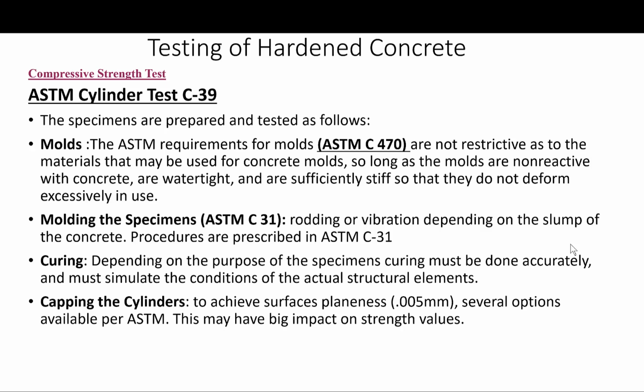If you refer back to the testing lecture early on in the first module, okay? For the slumps between 25 and 75 mm, the specimen may be consolidated either way, okay? So the specifications for a particular job may require a certain method of consolidation.